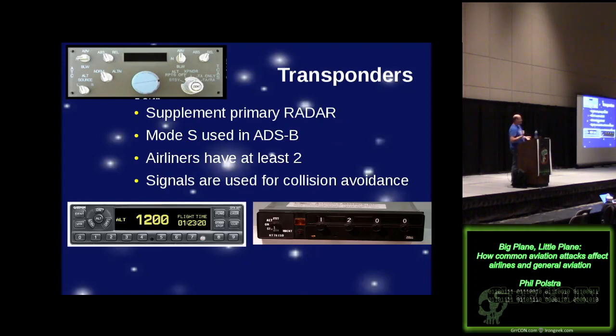Instead, what they use is a transponder signal. So transponder, if you don't know what that is, it's basically a little box in your airplane. When radar hits it, it goes, hey, someone's looking at me. I'm over here, right? And I have a little number. So you look at the bottom screen, you see 1200 is on the display. That's the I don't have a code, right? And it also sends things like your altitude, right?